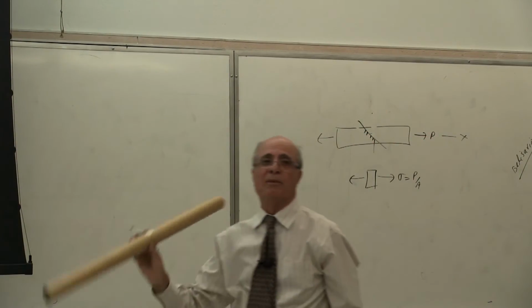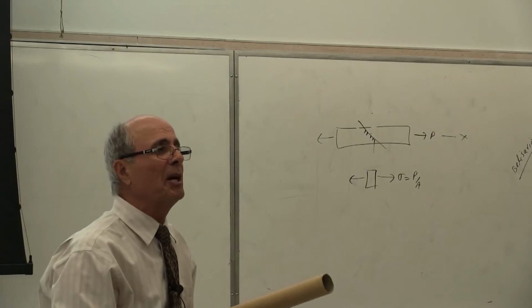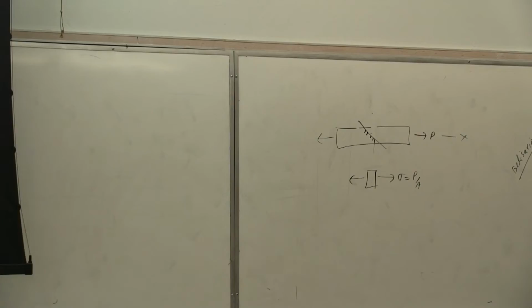There, what do we have? We have one sigma and we have one shear. It's more complicated. This is that. So when we were there, we can use geometry to come up with the stresses in the x prime direction and y prime direction. Actually, I did it. Some of you recall, I ended up with these two equations. Remember that? Cosine square theta and sine theta cosine theta.